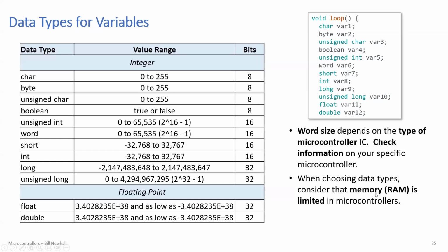But in microcontrollers, especially when you're using arrays, so if you have to store 100 values, would you rather use 100 bytes, right, if you have an 8-bit word, or 400 bytes with a 32-bit word? So you can really eat up memory if you have arrays of data types when you don't need that large range. And floating point math is often slower. So if you have to run a fast program, you have to do some fast calculations, and you can stick to integers, then there's often ways to use integers to do faster math.